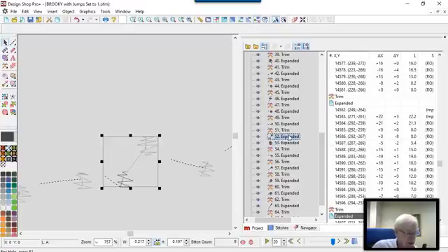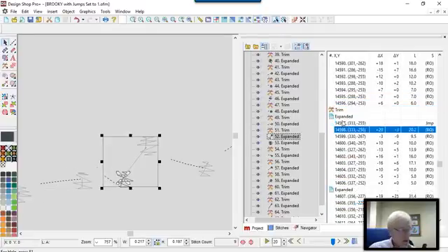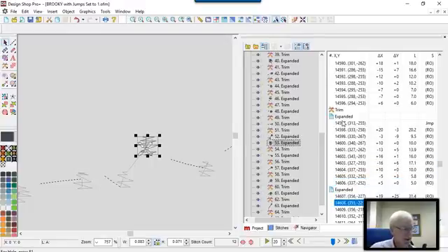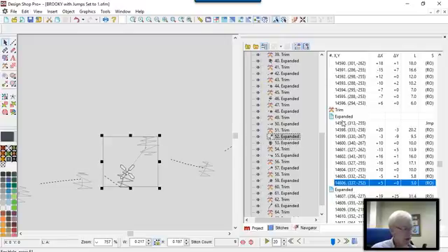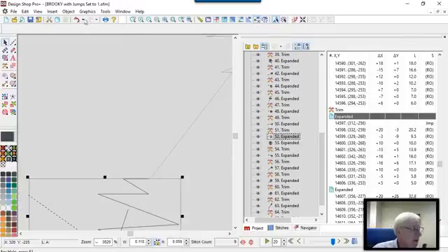So let's see still what happened though. It's not trimming. Well, it is trimming, it's just that I need to change the location of this long stitch as it's associated with the second dot. Alright, so I come in, come to here, I stitch my letter, boom. It's going to trim there, and that's where I'm going to go. So I'm going to come back here, and I'm going to drag this stitch, because once it's highlighted, I can move it up. Sorry. Undo that.